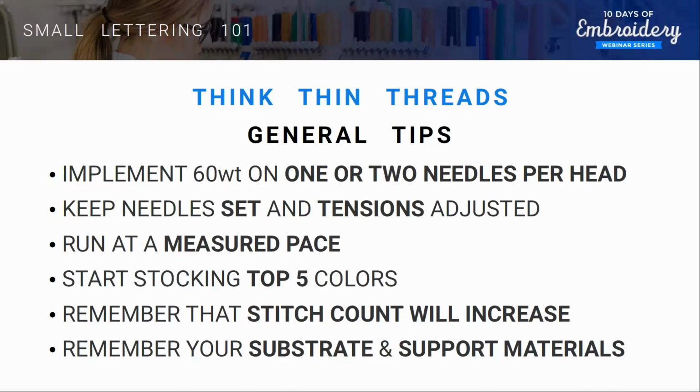That way you're not switching back and forth, messing with tensions, trying to change your needles out. Leave those couple of needles there just for doing the small lettering. It will be useful for you, and then you can just leave your couple of most popular colors ready to rock on that 60-weight thread on each head.